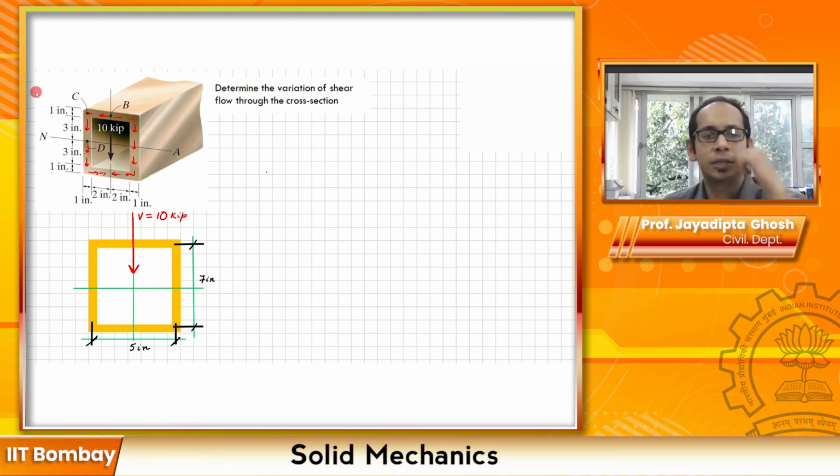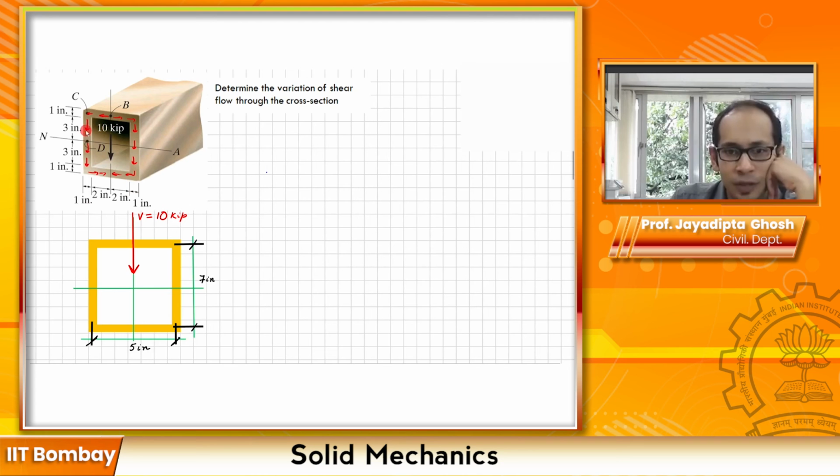So this you can imagine as the flow of shear is going to be. Also, one more thing, remember that for the faces which are perpendicular to the direction of the shear, the variation of the shear force is linear. That was one of the things we concluded, right? Also, in the face which is parallel to the direction of the shear, you must have the variation is parabolic.